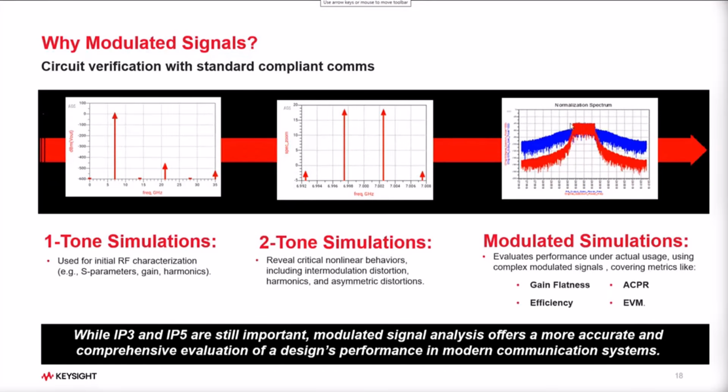If you deal with this kind of signal, which is not only wideband, it has a very high peak to average ratio. Look at all OFDM waveforms. They have a very high peak to average ratio. So your PA has a huge dynamic range which it has to handle in the signal. So how about gain flatness? How will efficiency suffer? What about ACPR or ACLR? Because in any communication standard, you're allowed to emit in your band, but you're not allowed to emit energy in the nearby or adjacent bands where somebody else might be operating. So you have those restrictions to worry about.